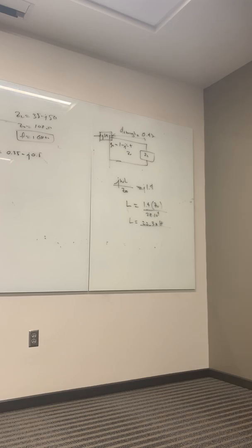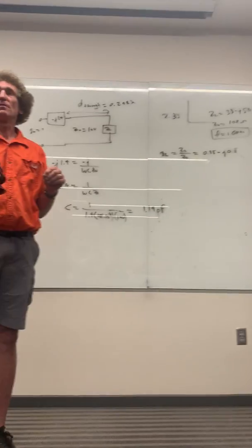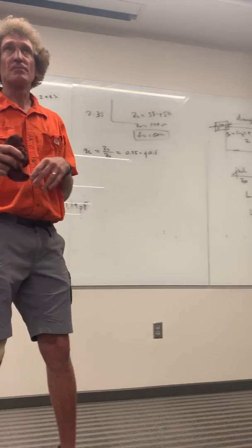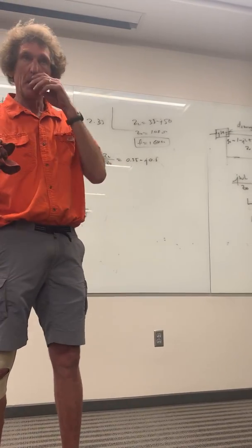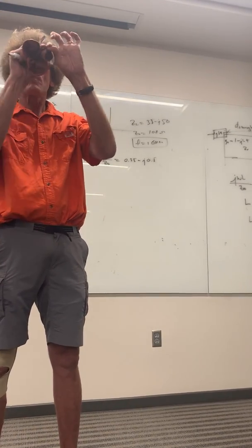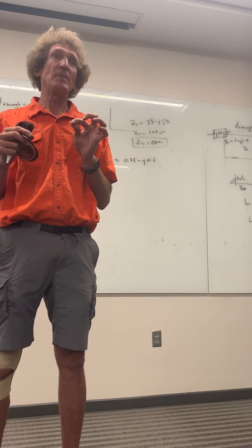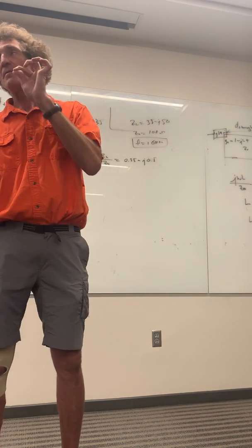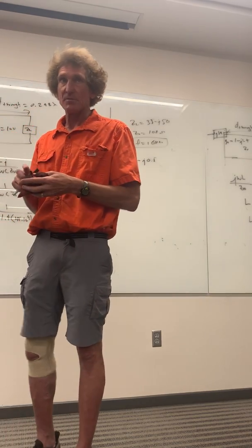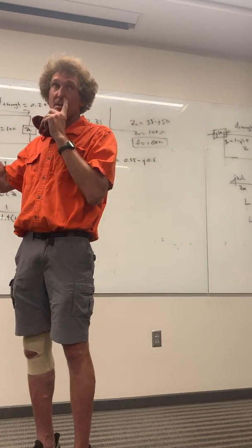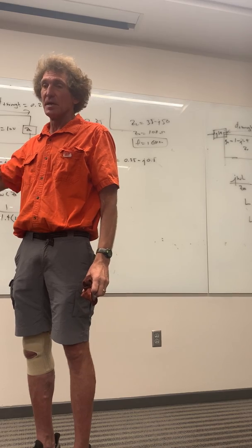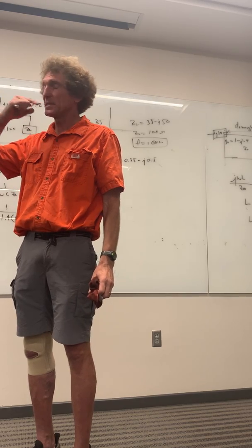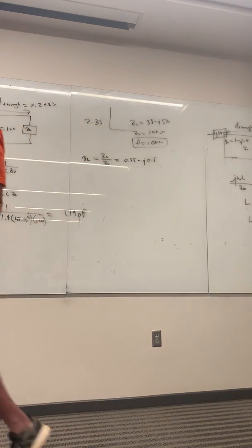And here's why. You say you need a capacitor of say 15 picofarad. A piece of wire with a little bend in it can easily have picofarads of capacitance at that frequency. It becomes very, very hard to get exact values for any components to do matching at high frequencies. You almost need tunable devices, and I had experience with this when we did a design project. It was a senior design project, and we took a CB radio and turned it into a ham radio.